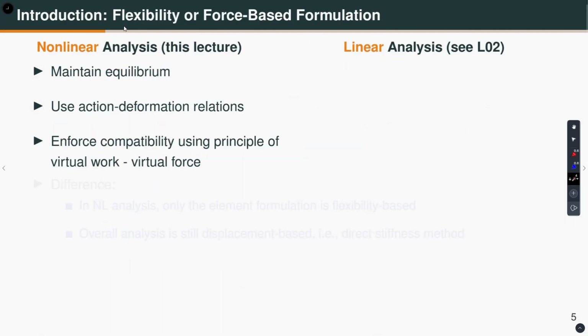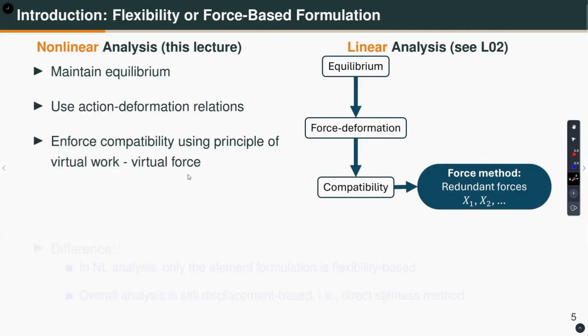On the other hand, what we will do today for the flexibility or force based formulation is maintain equilibrium first, and then we will use the action deformation relationship, and finally we will enforce compatibility using the principle of virtual work, virtual force. What we did for linear analysis, if you remember, in the force method or flexibility method, we start with equilibrium, then we use force deformation, and finally we enforce compatibility and solve for unknown redundant forces, which I am denoting x1, x2 and so on. This was again discussed in lecture number 2. So, you can see that basically they are identical. Okay. The approach is identical.